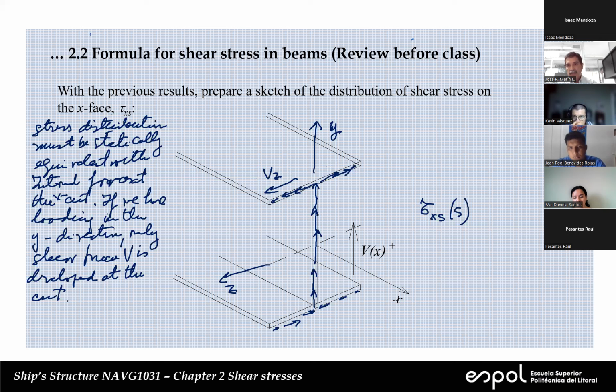Because you can see on the right-hand side, this will also produce a force in the Z direction, and this will cancel that one. Similarly, in the lower flange, we're going to have a force to the right and a force to the left. Again, this will cancel and we're fine.